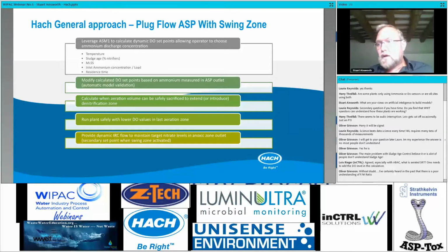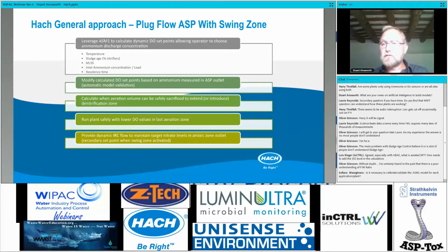fragilities of the existing DO control as well, which is one of the reasons we developed our MOV controller, because we were kind of hamstrung by other control strategies for aeration control. So we took it upon ourselves to improve the DO control to make sure that the plant can actually respond to our DO set point. Okay, so that's our model to deliver the correct DO set point for nitrification.